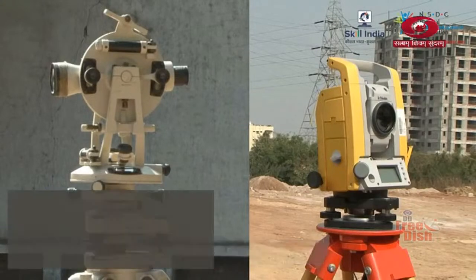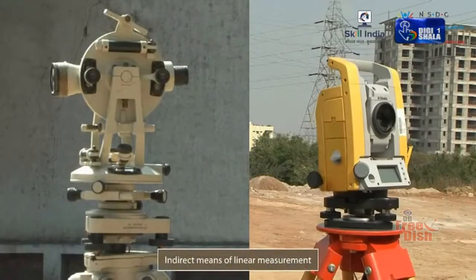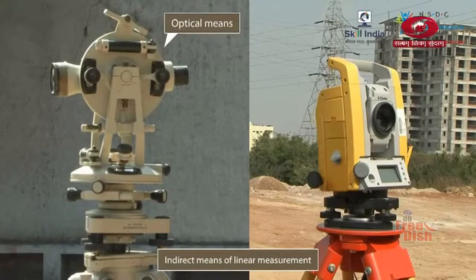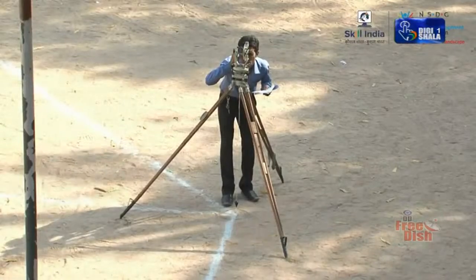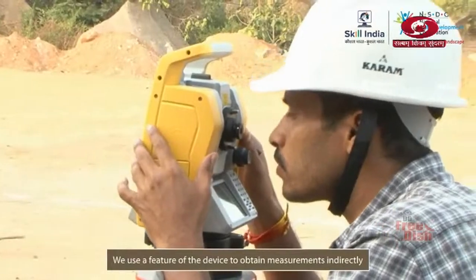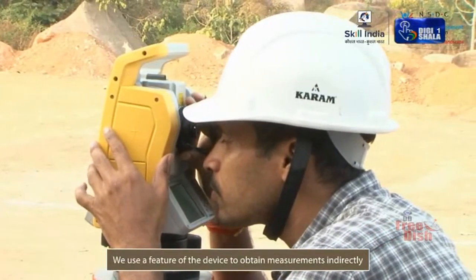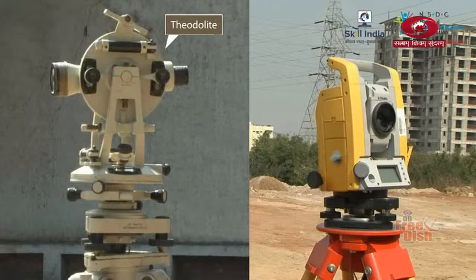Welcome. After completing this module, you will be able to. The two indirect means of linear measurement are by optical means and by using an electromagnetic device. We describe these devices as indirect means of taking linear measurements because we use only a feature of such a device rather than the device itself for taking measurements. While the optical device we use for linear measurement is called theodolite, the electromagnetic device is called total station.